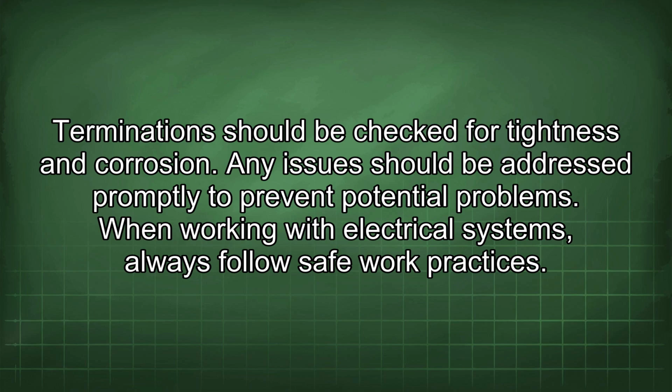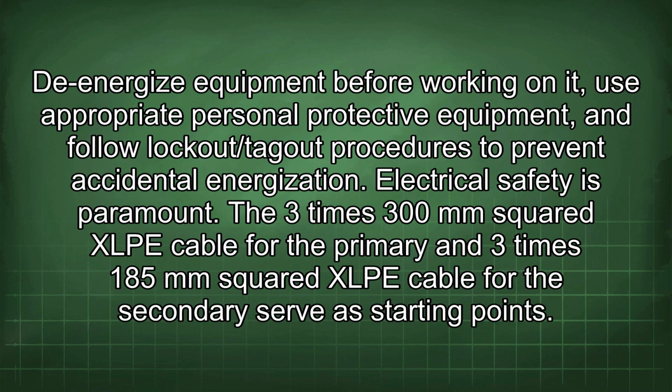When working with electrical systems, always follow safe work practices. De-energize equipment before working on it, use appropriate personal protective equipment, and follow lockout/tagout procedures to prevent accidental energization.